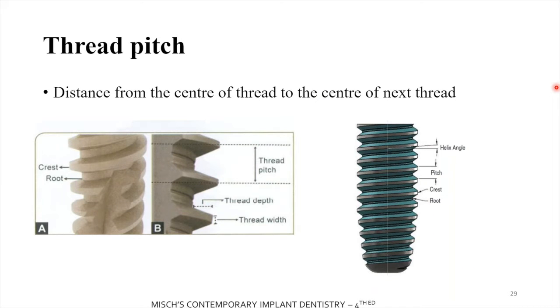Thread pitch is the distance from the center of the thread to the center of the next thread. This is measured parallel to the axis of the screw. Maximum effective stress decreases with the decrease in pitch.